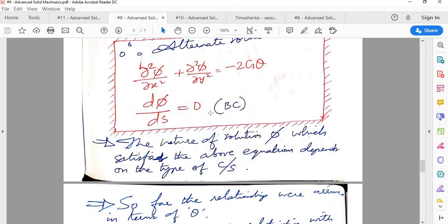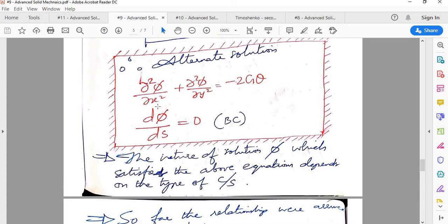In the case of solid sections, we know that there are different types of sections: annular section, solid section, channel section, many types. When you have a solid section, whatever the shape, parabolic, elliptical, square, rectangle, as long as it's solid, phi can be chosen arbitrarily.